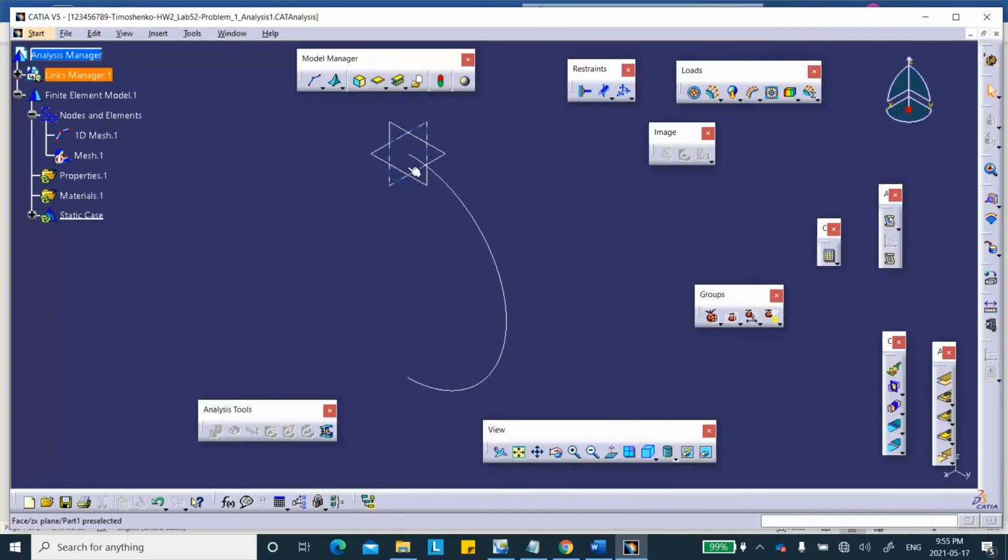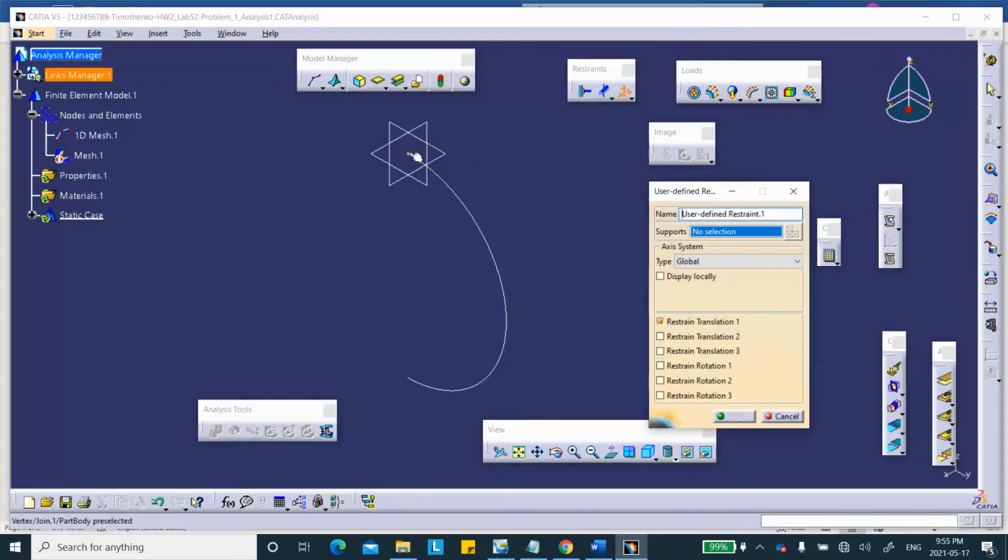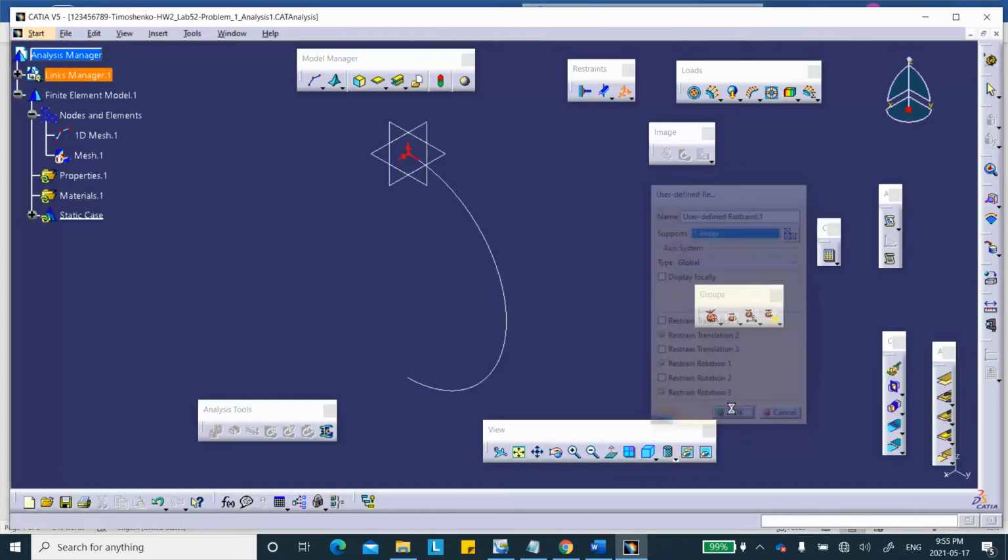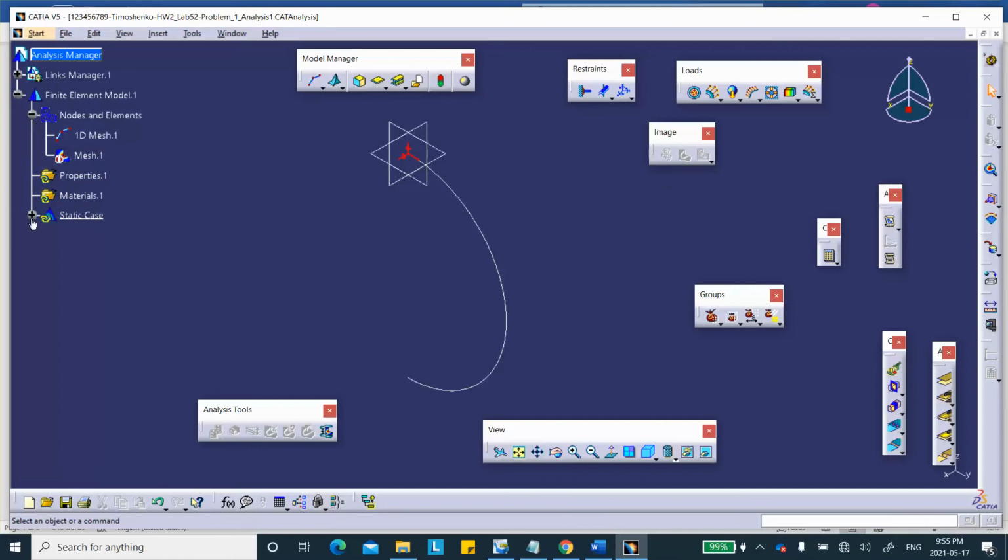Now, this top point being in the plane of symmetry xz does not move in the direction y, okay? If a point of the beam lies in the xz plane of symmetry, it does not move in the direction y. XZ plane, no displacement in Y. Rotations, exactly the opposite. So if this is checked, corresponding rotation is free. If these translations are fixed, corresponding rotations are free. By the way, this applies also to the bottom.